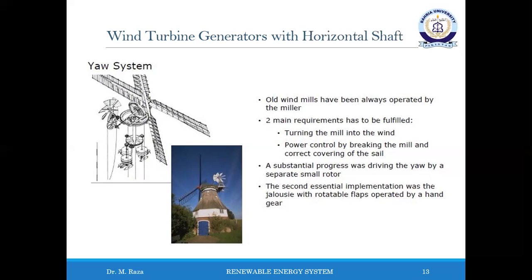The adaptation of the power consumption by the rotor to the prevailing wind speed was far more crucial. For this purpose, more or fewer sails were put on the sail frame of the windmill blade. This was a risky issue, especially when the miller underestimated the wind and suddenly a strong breeze or even a storm came up, and there was the danger of an overspeeding of the rotor.